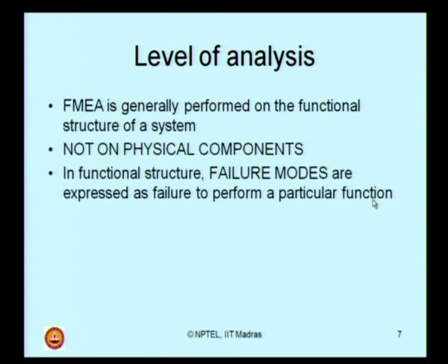Ladies and gentlemen, you can easily compare this scenario with what we discussed in HAZOP. In a HAZOP study, just for recapitulating, try to recollect that it has got two backbones. One is what we call a design intent, the other is what we call a deviation. Now, can you relate what the failure mode is with respect to, is it a design intent or is it a deviation?